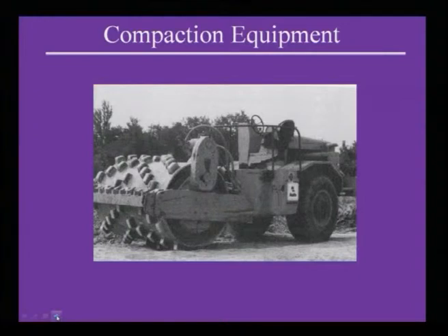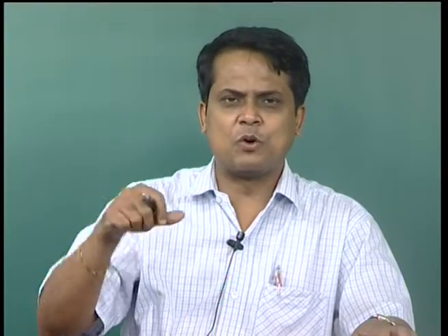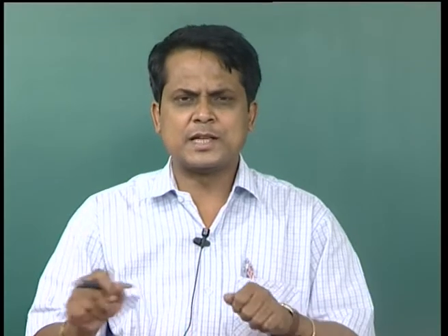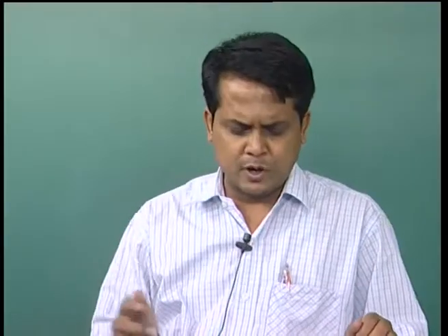Look at this. These are all sheep foot, which means there are some feet coming out of the drum. It will penetrate inside the ground. If it is clay soil, this kind of equipment is to be used. Now, look at this vibratory compactor. Suppose there is loose sand. By using a vibrator, you place it and it will vibrate. Particularly for loose sand, this vibration is done so that it will compact.